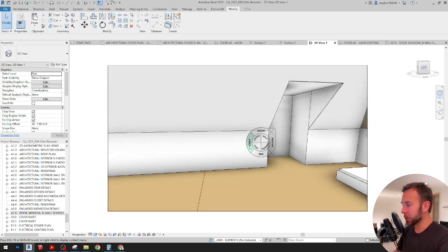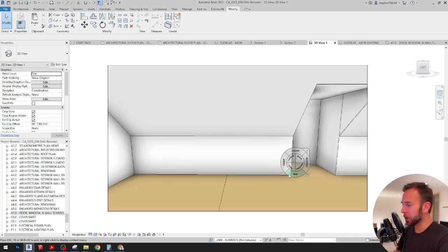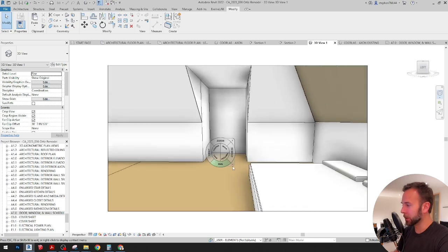But also, since you have the opportunity to plan for furniture, it doesn't hurt to just understand how some of these things are going to interact with maybe a king-size bed that's put along this side of the wall. So you can see, that dormer space, if you had a bench or kind of a reading nook, clears the foot of the bed so that it lines up nicely geometrically. So another thing to consider will be where the rafter ties come in. If it's on a regular rhythm, probably wanting to center this dormer on that same rhythm of the rafter ties.